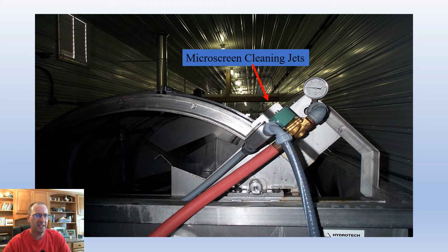And this might happen several times a day on a system that had a lot of suspended solids in it. The only downside to such a system is you have to monitor the water flow pretty carefully, because you can overdrive the system with too much water going through it. You actually strain the dirt right back through the microscreens. We've had that happen before in testing on some systems that weren't properly designed.